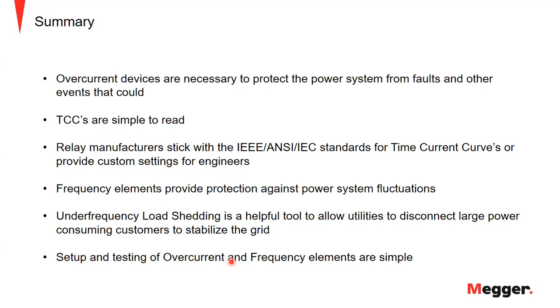The relay manufacturers go by specific standards, but, like I was saying earlier, they also provide custom settings, so you can create your own inverse time curve in case the ones that they have are not reasonable enough for your coordination.